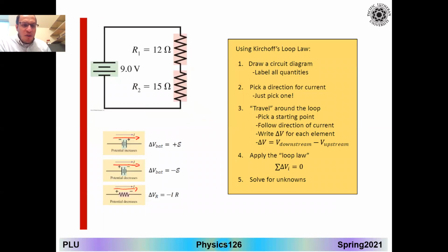See with this example how we're going to solve the circuit based on the Kirchhoff law, where we basically need to identify the sign of the voltage or the current through the element. Here I listed something to make sure. The first one: you assume the direction of the current. So you select the direction of the current.